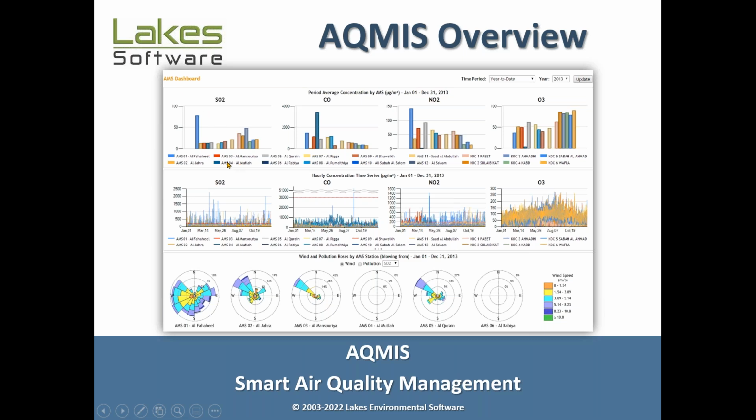So you have different monitor stations indicated here and their concentrations. And you can see this curvy line because this concentration was so high. If we had plotted them, these other ones would show so small, you wouldn't see them. So then we cut it here. The red line is the regulatory limit for CO for this jurisdiction. So we put this red line on all of them, and we know if it is exceeding or not.